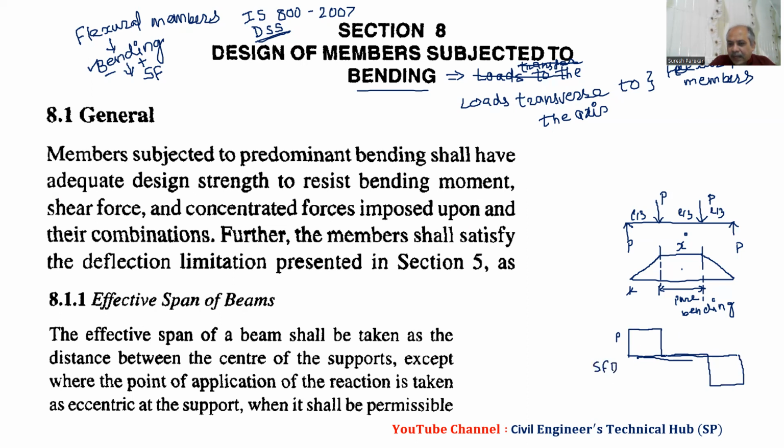As we do not have any shear in this L/3 portion, you will see x to the power 0 in the bending moment portion, and this is pure bending. If we take the other portions, then we have shear force plus bending moment.